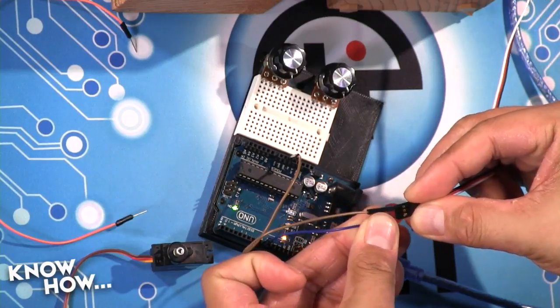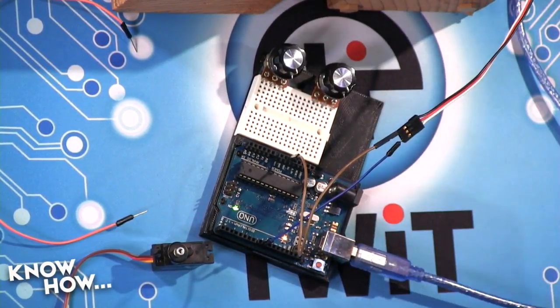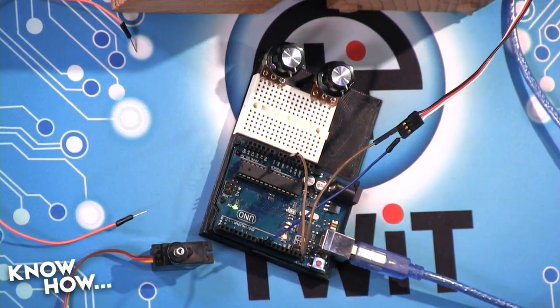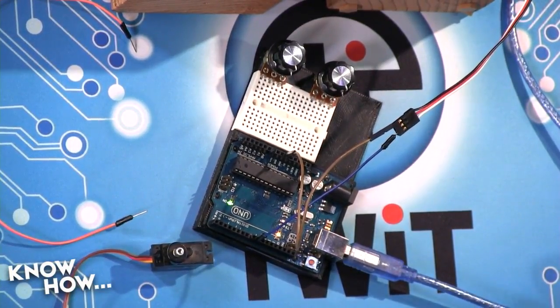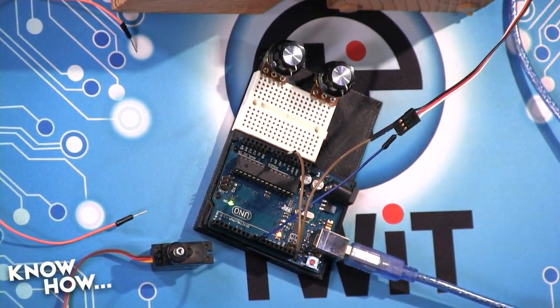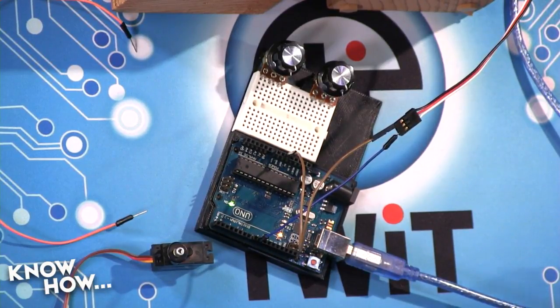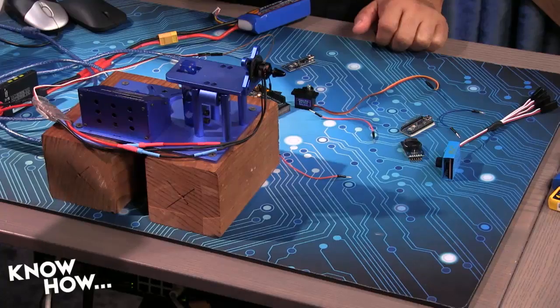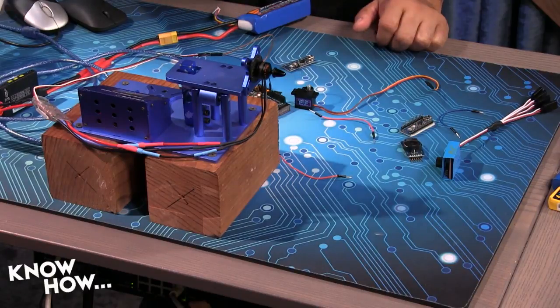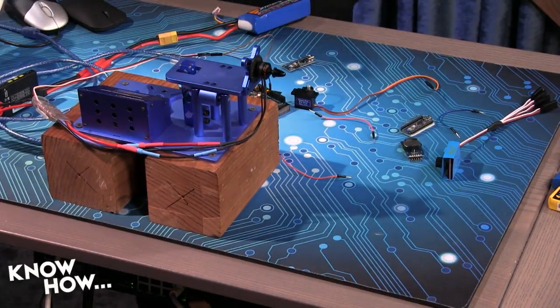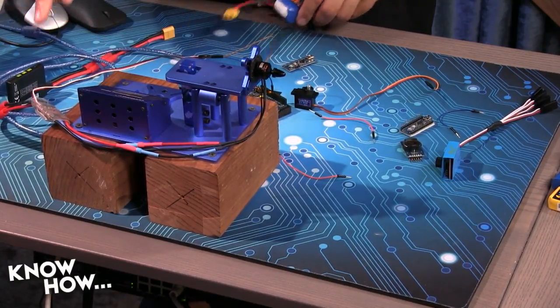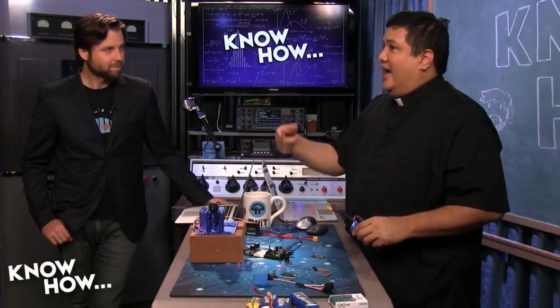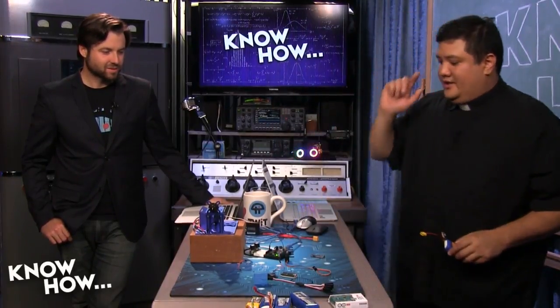And then you're getting power from a battery? I'm getting power from a battery, and so if I plug this in, like so, there we go. So now you're able to spin that. But see, you can hear it sweeping, so it's going up and then down, up and then down. So it's doing exactly what the servo did, but the difference here is the ESC is actually interpreting that signal and telling it how fast to throttle up. Right. It's interpreting it as the throttle.